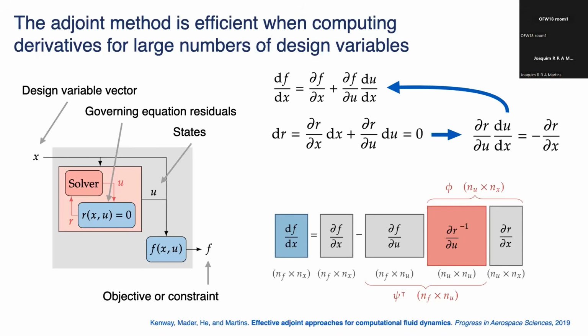And that's the whole key for the adjoint method, right? Because now you can have thousands of variables and a few functions. If you have a few functions, many variables, adjoint works wonderfully. And that's why it's so useful in aerodynamic optimization and other MDO problems where you have a few functions of interest, a lot of design variables. And that's been the key for all our work.